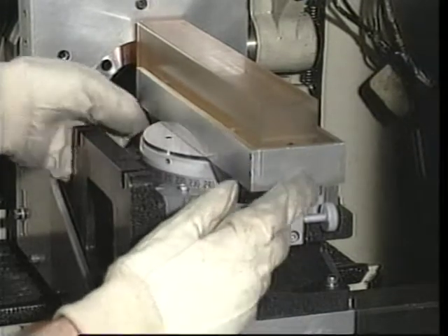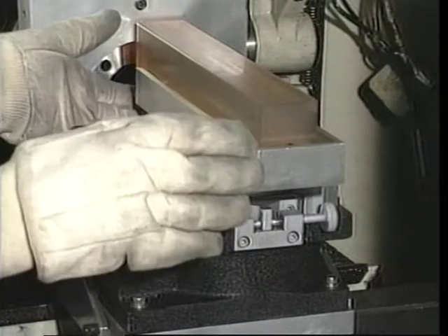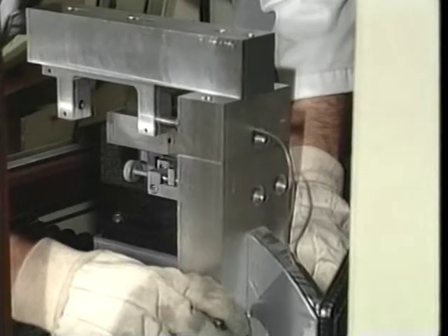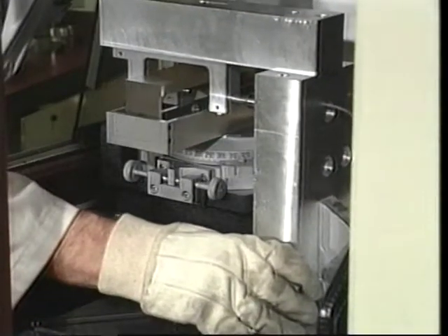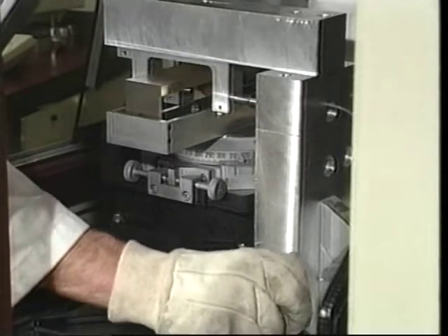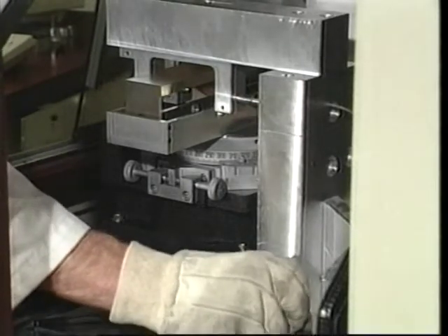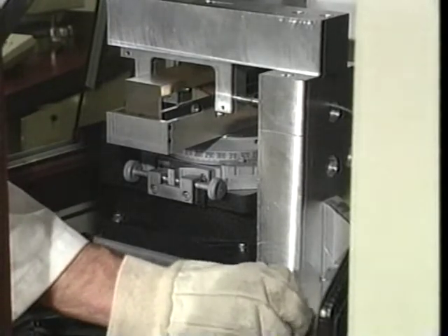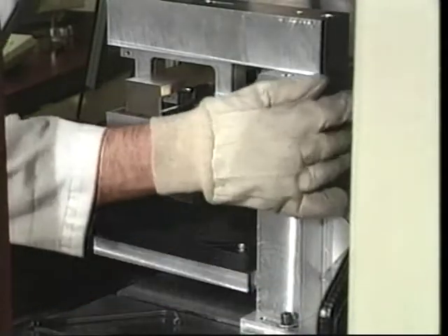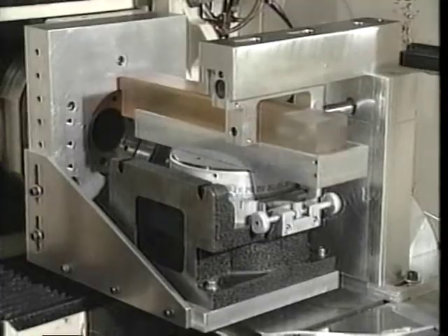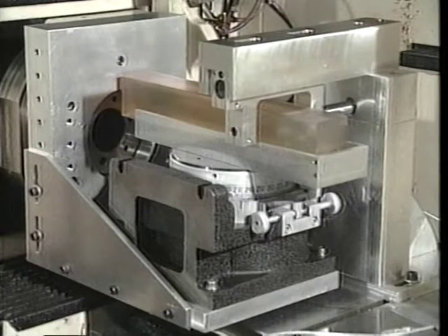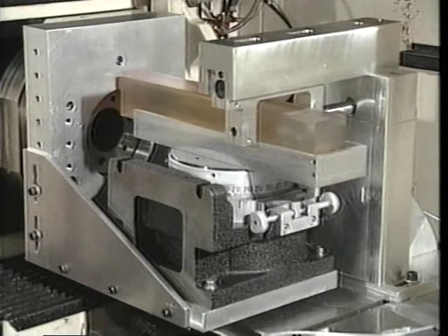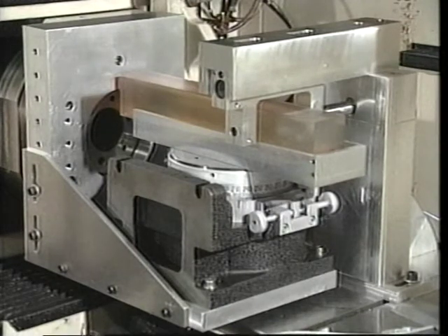The position of the straight edge is checked to ensure that it is still positioned against the locating balls of the kinematic cradle. The probe is repositioned so that it again senses the reference surface of the straight edge. Effort is made to reposition the cap gauge such that it will probe approximately along the path probed in the first step. The capacitance gauge readings are then recorded as the z-axis is moved through its range of travel. Note that in this step, the straight edge is moved past the probe mounted to the stationary x-axis slide.